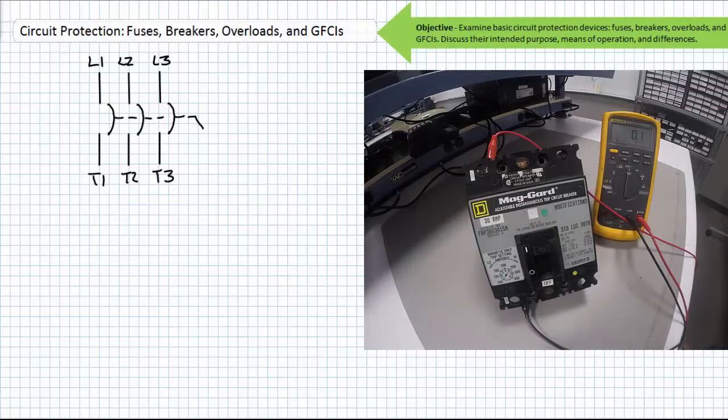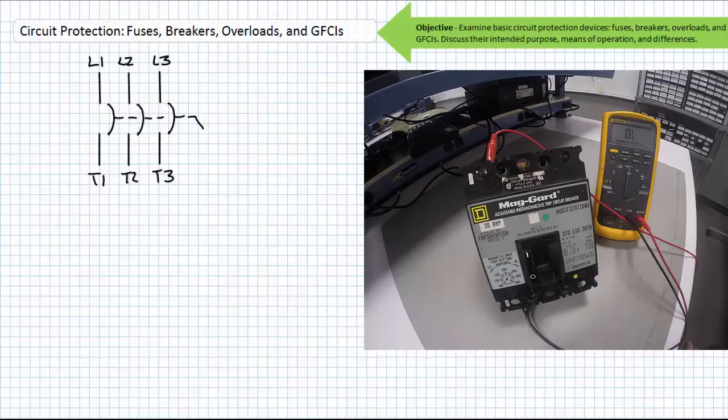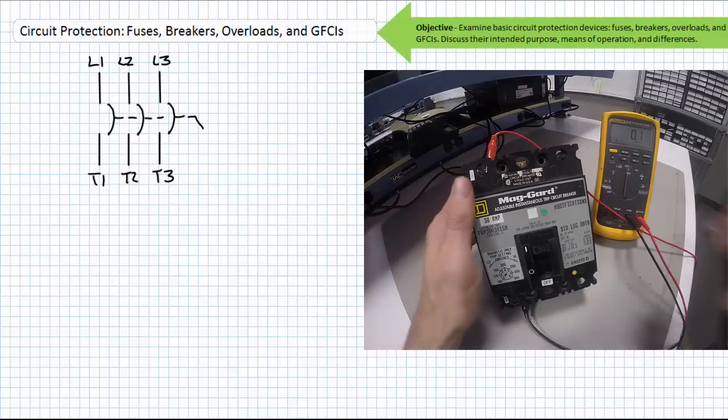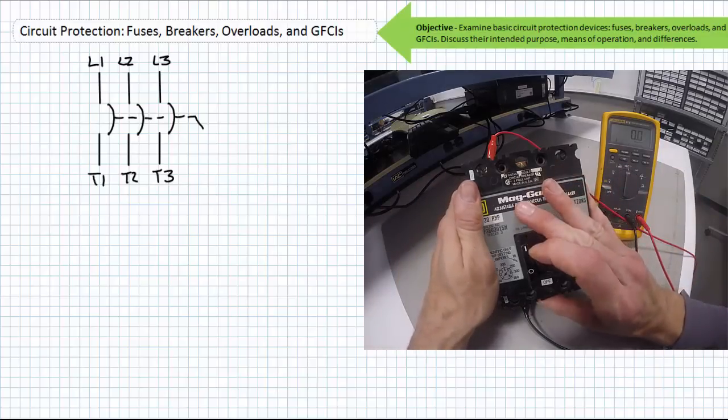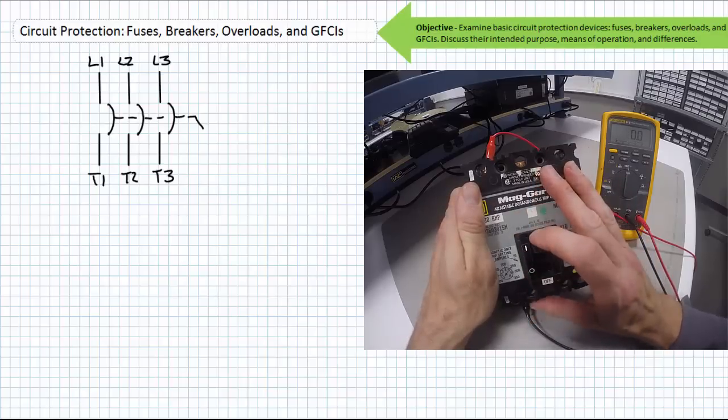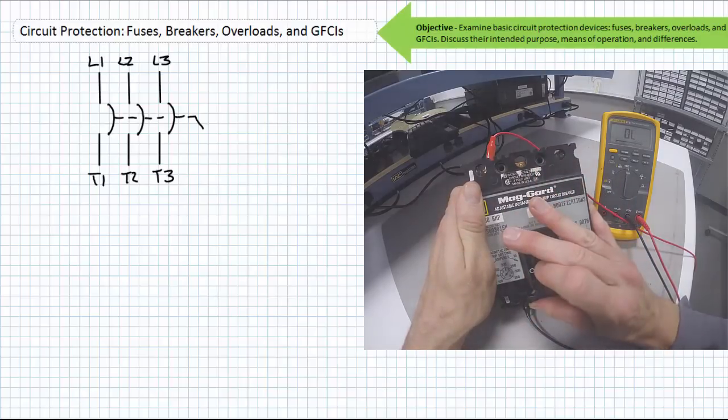Here's a three-phase circuit breaker removed from a circuit. In its closed position, the L1 to T1 terminals present almost no opposition to current. When it's automatically or manually tripped, it opens and forms a large resistance through which no current can flow. Unlike the fuse, though, the circuit breaker can be reset into its closed position. Here's a video clip of the switching action. Notice the sound which the circuit breaker makes. It's a satisfying snap, and you can really feel a jolt when actuating it.